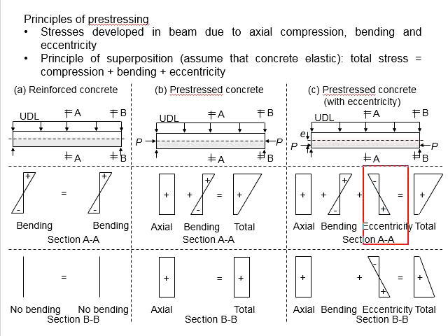There is one more consideration here, which is due to the effect of the eccentricity. When the compressive force is applied at an eccentricity lower than the neutral axis, it will generate high compressive stress at the bottom of the beam, which subsequently shortens the bottom part of the beam and leads to tensions at the top of the beam. This gives a compressive stress at the bottom of the beam and tensile stress on top of the beam.